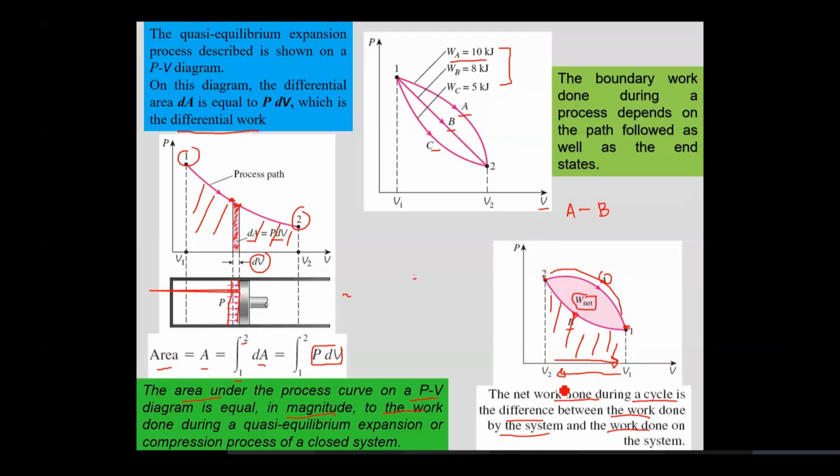If I take the system from 1 to 2, I am doing work on the system by compressing it. And if the system moves from V2 to V1, the system is expanding, so this work is being done by the system. Anyways, in a cyclic process, following two different paths between the same two states, you will have some net work available to you. Is that clear enough?